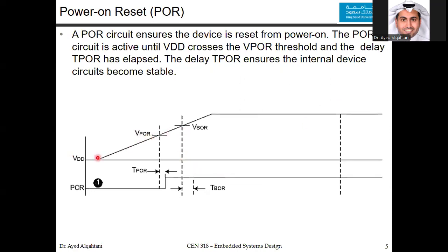And now you should understand why it's more than the VPOR. For the VPOR, you know that the VDD was 0 and you are moving up, and that's why this threshold is less than the VBOR. For the VBOR, the VDD was at its normal level. It was high, 3.3 volts in our PIC24. And then at a certain level, it goes down. Once it reaches this voltage, it tells you there is a brownout reset.